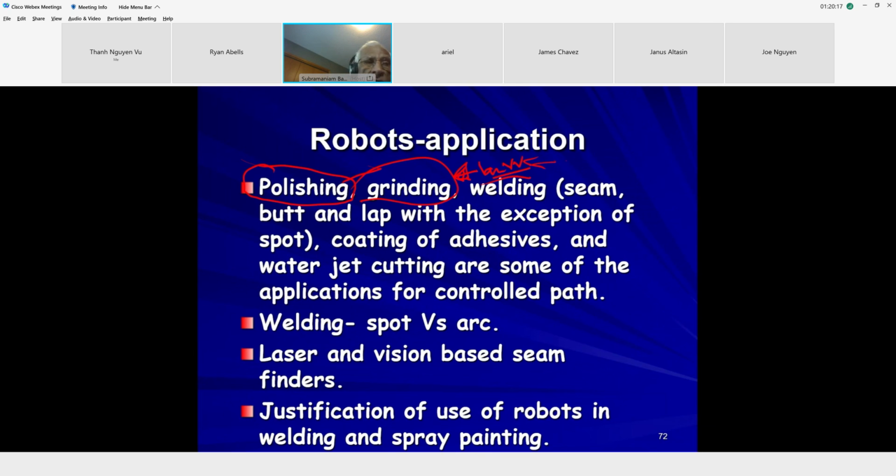When these parts go into the wing at high altitudes, the aircraft wings are not inflexible. They do flex quite a bit, sometimes as much as 6 inches tip to tip. From what I heard from them, if those parts are not rounded, it produces sonic resonance. As a result, premature failure may happen. So it is the military spec regulation that they have to be rounded.